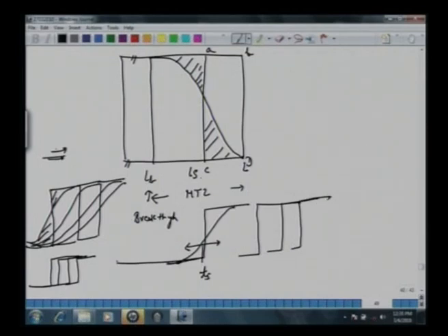So coming back to this, we have defined this LS, the length of a stoichiometric front. We can call it an ideal front, so this area here is like this, and we can say that the entire area here is unspent, and we call it LUB, the length of unused bed. So the MTZ is approximately twice this LUB. Equivalent to this, if we draw a response here, we have the front like this.